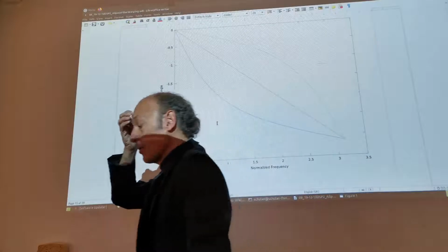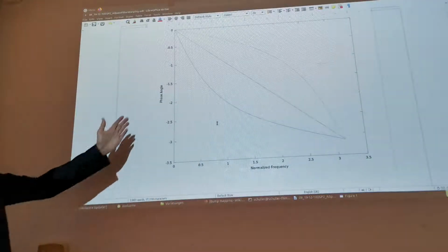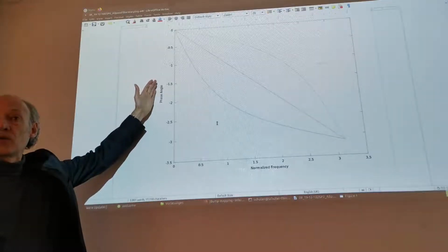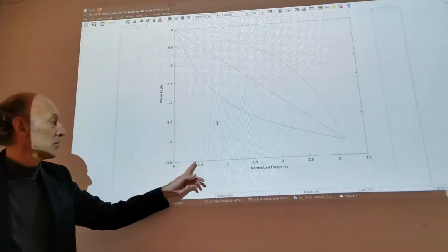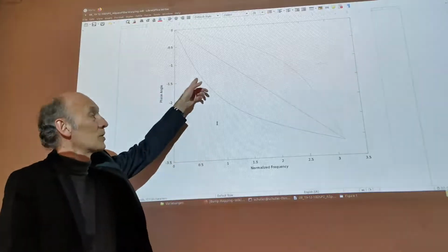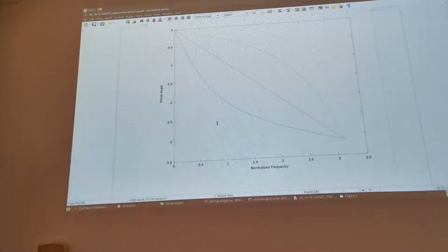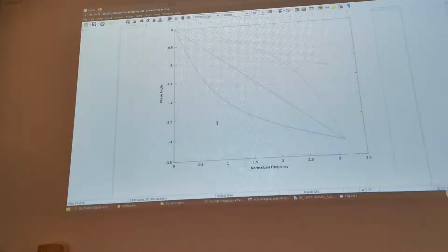Frequency warping relies on the idea that we can interpret this angle also as a normalized frequency. That means we map this frequency range 0 to pi, 0 to Nyquist, again to 0 to Nyquist if we take the minus sign away. Then we have a mapping from frequency to frequency.